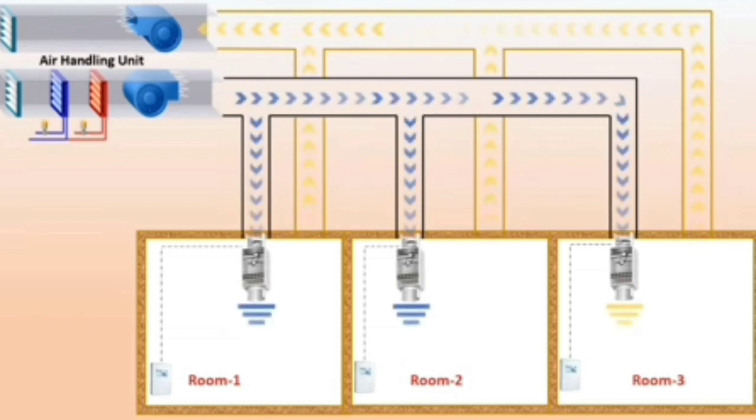For example, room 1 and 2 are being cooled while room 3 is being heated through a heater installed inside the VAV box. As airflow through the VAV box changes, it results in change of air pressure inside the main supply duct. For example, if VAV damper of room 1 closes, it will result in high duct pressure inside the main duct. Similarly, if VAV dampers are more opened to provide more cooling inside the rooms, this will result in low duct pressure inside the supply duct. So we must control the supply static pressure to maintain the designed value to ensure proper airflow to the rooms.